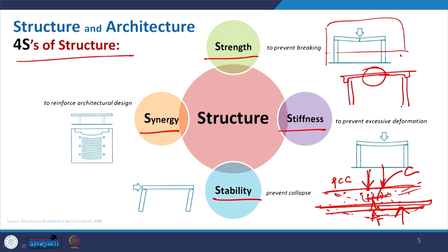For this kind of slab, we put the reinforcement in the lower side of the section, okay, so that this will take care of the tension. So, it will give a balance between tension and compression, and finally we will have some equilibrium. We will come to that and discuss with some experiment also, but anyway.